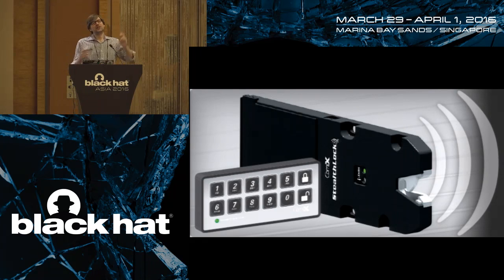So finally, some months later, Taylor and I in the lab decided to get this out and play with it again. And he decided to take apart this remote, since it didn't seem to be working properly. He had to peel the PCB off of the membrane keypad. They were stuck together, and it turned out that it basically had buttons held down all the time. Once we unstuck them and put it back together, everything worked fine.